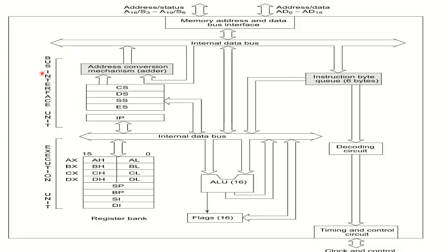The main function of the bus interface unit is to provide the interface between the processor and the outer device, that is, the memory. As we know, the data or instructions are loaded or stored in the memory. The bus interface unit fetches the instruction or data from this memory. This is the outer memory, and this whole thing is the 8086 processor.